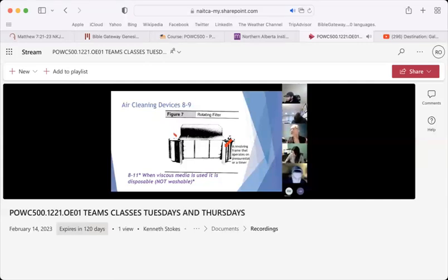So there's a roll of filter material in one end of this device, and it will roll across. And it can be on a timer, it can be on pressure measuring equipment. So pressure on the downstream side of a filter gets lower and pressure on the upstream side gets higher. I could turn on this transport for this media and move clean media into the revolving frame.